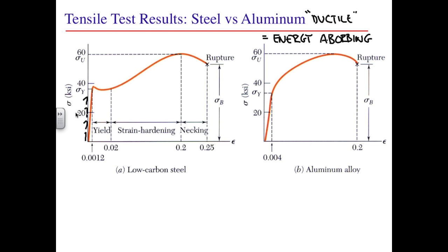With respect to the steel, for instance, I'll use these arrows to indicate I'm climbing up the stress-strain curve as I increase the load, and let's suppose we increase to this point. If I then unload it, I'll come right back down this stress-strain curve and go back to both zero load and zero deformation. This is the desirable operating space for any structural engineering application.